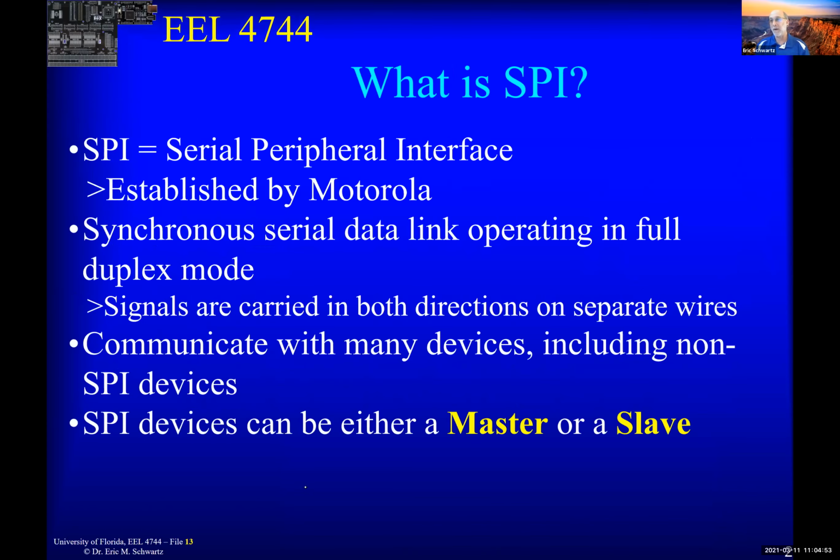Okay, so why do we have SPI? Because with asynchronous serial, you see there's some overhead, right? You had the quiz, there's overhead. Every time you want to send, let's say, 8 bits of data, it takes an extra start and stop bit, at least, maybe a parity bit as well. That's 10 bit times if we have 1 start and 1 stop for only 8 bits of data. So we're losing, depending on how you calculate it, 25%, wasting 25% of the time, or 20%, whichever way you look at it. Okay, and so we want to get rid of that.